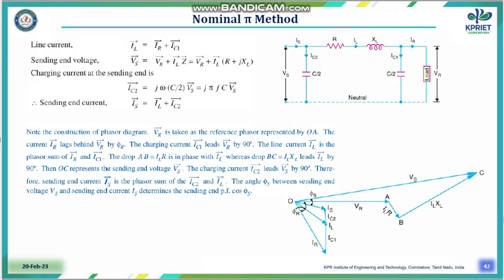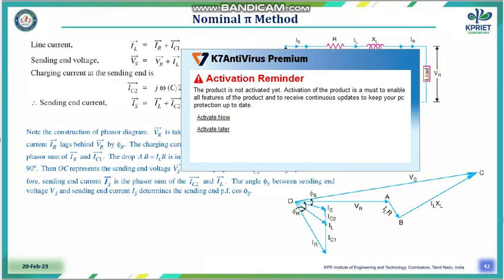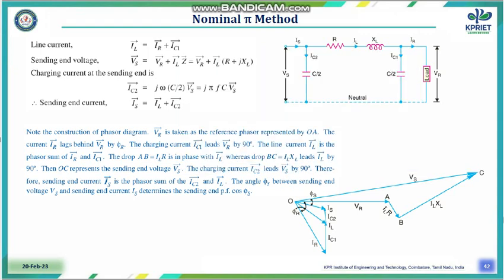These three methods are used to calculate the performance of the lines. From this we can determine whether the line is inductive or capacitive, based upon the angle direction, whether it is plus or minus. If it is negative, the line is considered a lagging line, and if it is positive, it is considered a leading line. With this, we can read the performance of a transmission line.